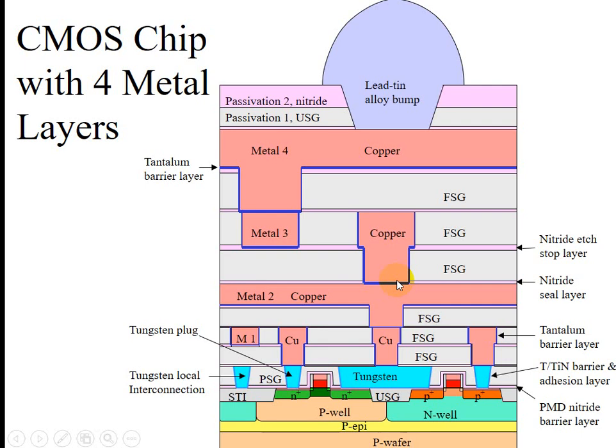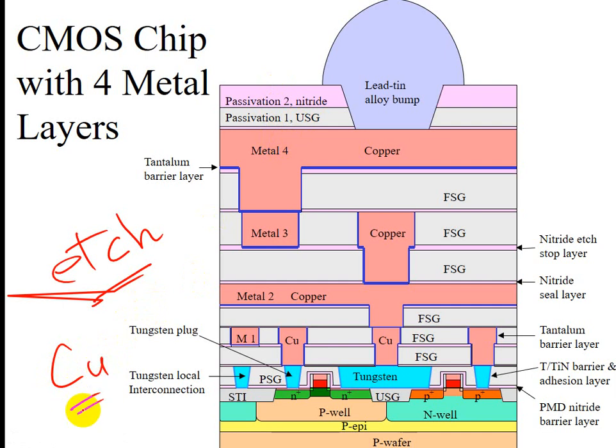Okay, because copper is looked at as a contamination for aluminum technology, because as we mentioned, you can use a process or etch process to remove materials. Copper basically cannot be etched. Well, it's not really cannot, but it's very difficult for the process design. It's very difficult to be etched away.